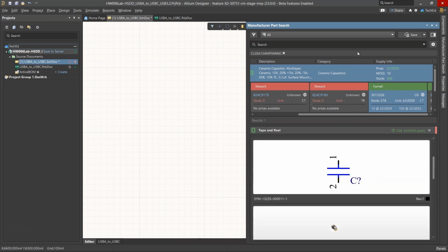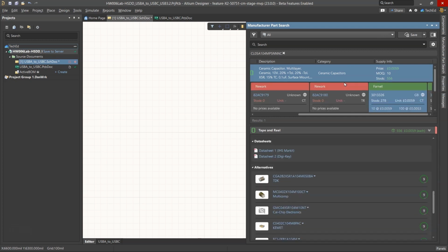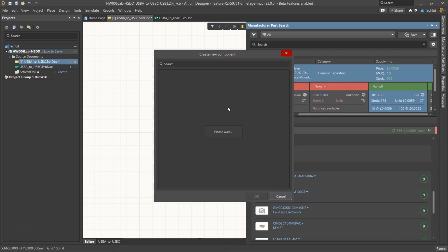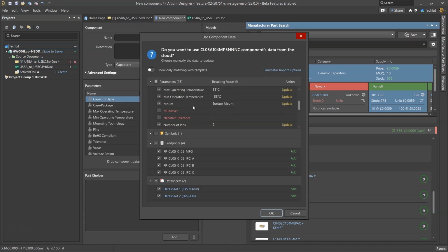So I'll add this here, right? And then this is the component device. Since this has the information I need, I'm going to save to my workspace, and I would add that to capacitors again. Right, then we have, you can add JEDEC codes, you can add, see if we have height. Yes, I want to add height. And the packaging, no, I don't want packaging really. You can have positive and negative tolerance, even package shape and package style. And rated DC voltage, that's important, right?